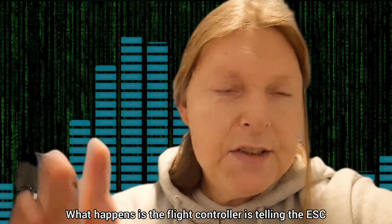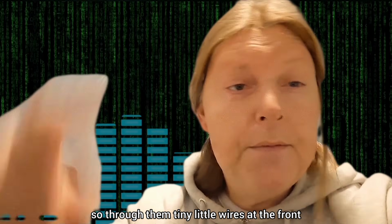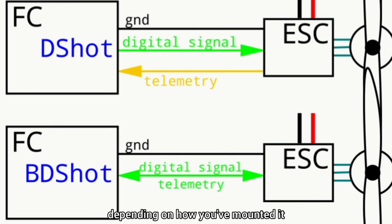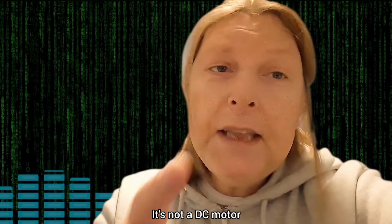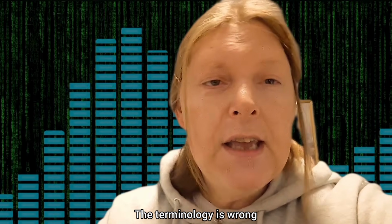What happens is the flight controller is telling the ESC, through those tiny little wires at the front or at the back, depending on how you've mounted it, it's giving it a PWM signal, and basically it's telling the ESCs to tell the AC motor. It's not a DC motor, don't get confused, the terminology is wrong.